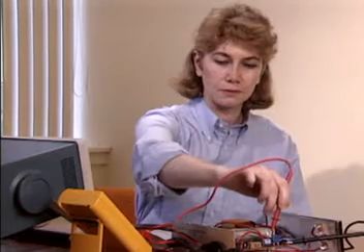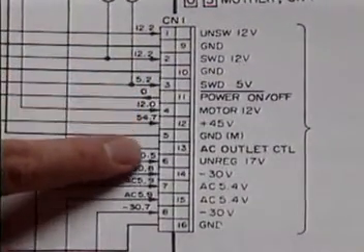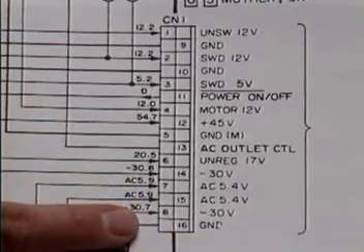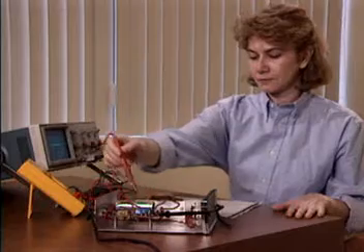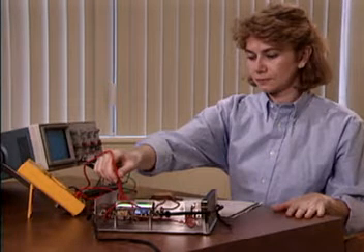Safety is the most important thing to keep in mind when working with electrical and electronic equipment. Here are 3 life-saving rules. Rule 1. Use one hand when testing and troubleshooting equipment. There will often be different levels of both AC and DC voltages within a single piece of equipment. If, in using 2 hands to troubleshoot, you accidentally come into contact with 2 different potentials of voltage, a current path is created directly across your chest cavity. The results can be deadly.